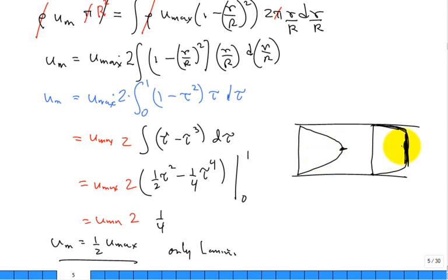And the U mean is maybe not 0.5 of U max, but maybe 0.8 or so of U max. It's going to be higher than 0.5 if it's turbulent flow. And you can get an analytic velocity profile to some power, and then do the math and find whatever coefficient it is. But it's higher than 1/2.